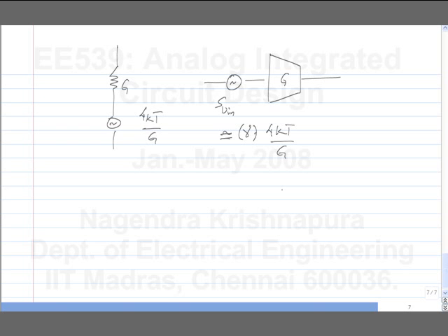But if you make a transconductance, you will have this much noise. Just like if you try to realize a conductance, you will have a certain amount of noise. You will have more than this, but you will have at least this much. So, this you have to take into account when you are doing analysis at the fundamental level. Let us say you have not yet designed the circuit and you just decide that, oh, I will have an amplifier here, I will have a transconductance here, etc. You can't just assume zero noise for all those voltage controlled current sources, okay. If you are making a voltage controlled current source, you will have a certain amount of noise. So, that you have to factor in. This is okay?